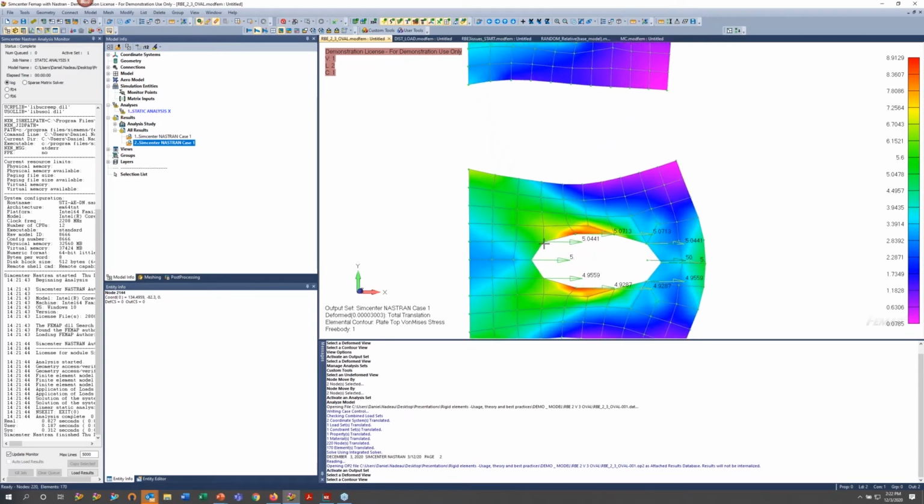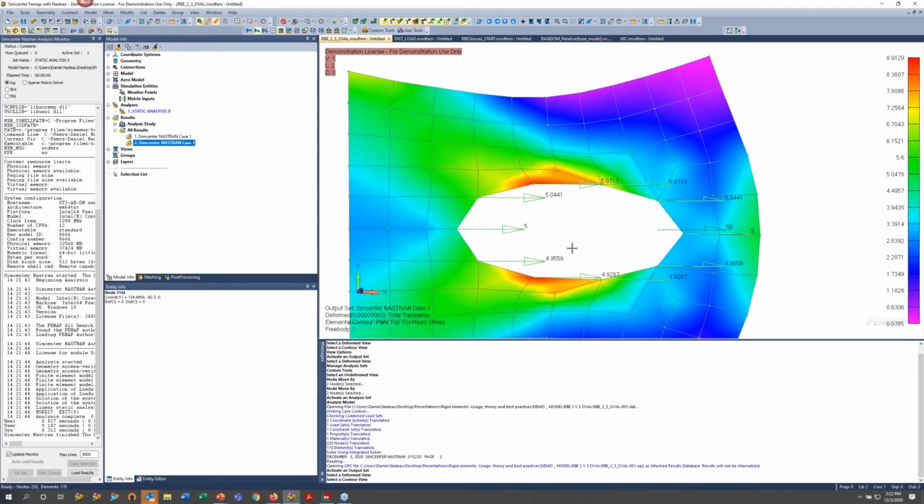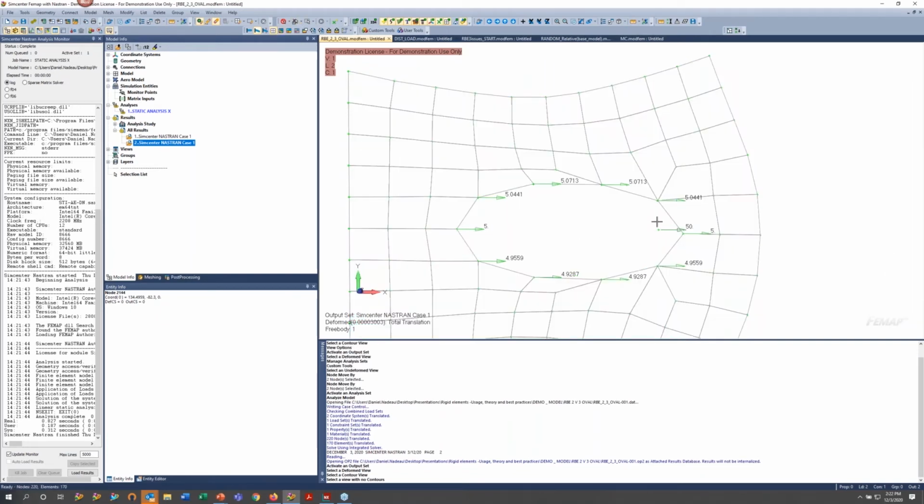And this one's still ovalized, but you'll notice that my reaction forces are not equal because the center has now moved up. So the length of the legs got a little shorter over here and a little longer over here. But in the middle, it still was halfway between each side. So that's why this load is the same as it was before, where this load on this half of the circle has increased a little bit, and this one has decreased a little bit.